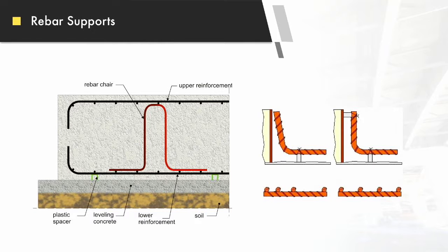So it's just another thing that I found that works well for me, is to get with the contractors before they start standing forms or setting rebar, and make sure that they know proper clearance, that you are going to be looking at it, and they need to chair all the way up the forms, so that you don't have this situation right in the left slide there.